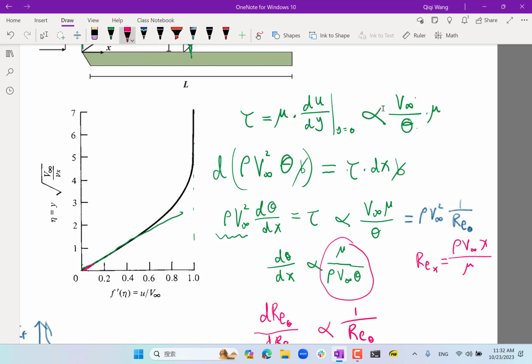On the other hand, the y-axis is non-dimensionalized. But if you actually increase the thickness by a factor of 2, right, increase theta by a factor of 2, so if you, instead of plotting the non-dimensional y, you plot the actual y-axis, increasing theta by a factor of 2 just stretches this picture upward by a factor of 2, which decreases the gradient by a factor of 2. Right, so essentially u infinity over theta is a scale of the dimensional version of the picture that gives you the dimensional slope of du/dy at y equal to 0.